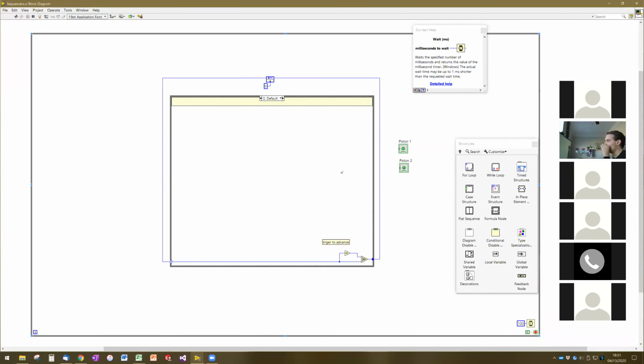Okay. So one of the things that would be typical for us to do if we were doing a climb sequencer would be say that piston 1 is going to pull some sort of release pin that extends the climber, and piston number 2, maybe that engages or disengages a PTO at different times during climbing. And so if during normal robot operation, both of these are false, the very first thing that we might do in the sequencer is to go ahead and set both of them to true. So we pull the release pin on the mechanism, and we go ahead and shift our gearbox into low gear or into the PTO state.